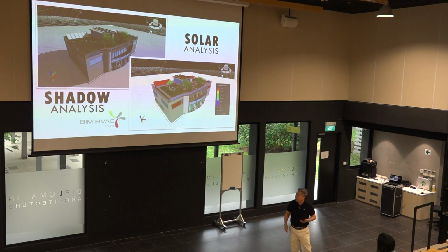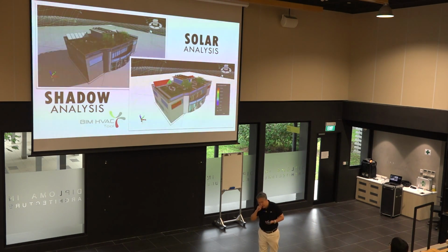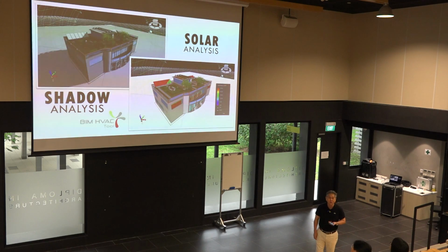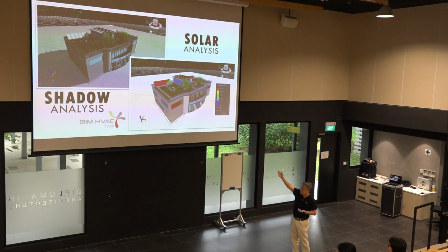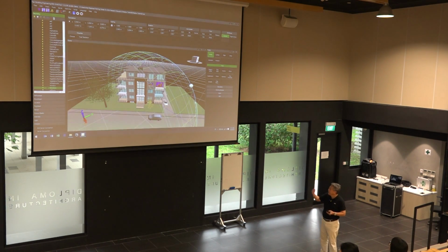All right. So now I'd like to highlight these pictures because a lot of people think that, hey, you have a flat roof on the HDB flat, on a high-rise building, you have the full area for you to implement PV panels, right? Yes or no? Wrong. When you go up to the rooftop, what do you see? You have lift shaft, you have water tank, right? So all these building elements, are they higher than the roof? Yes. So in other words, you don't install solar panels next to those building elements. Understand? All right. So a building like that is nothing.